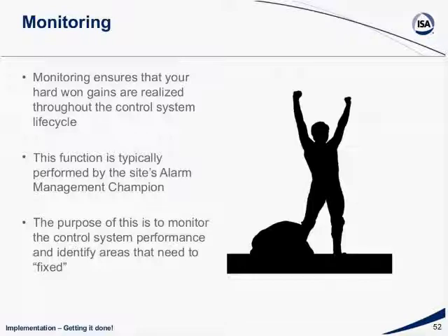But the importance of monitoring is that you spent a lot of time and a lot of sweat equity making system changes, making things better for the operators, for the facility, and for the shareholders of the company. You want to continue to realize those benefits. And if you don't monitor things, things tend to drift. You tend to drift back to what you had before. It's an interesting dynamic. I'm not exactly sure why it always happens, but it does always happen. And so the alarm management champion is going to be responsible for maintaining and monitoring the system as they go forward. And the periodic reports are really, really important.